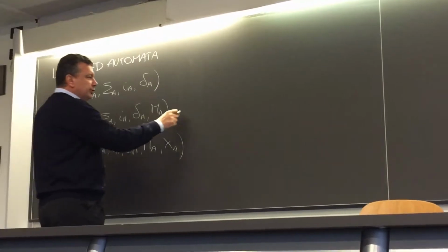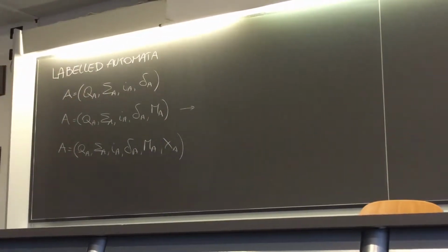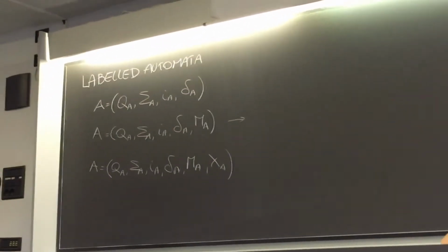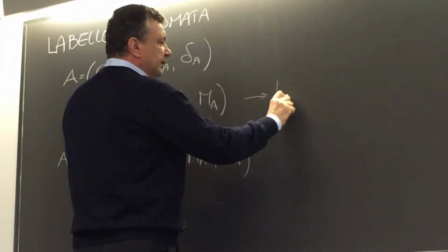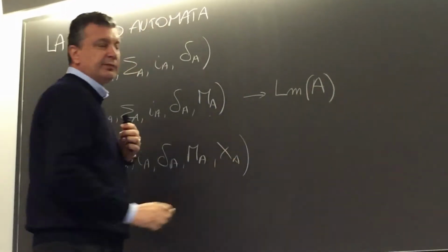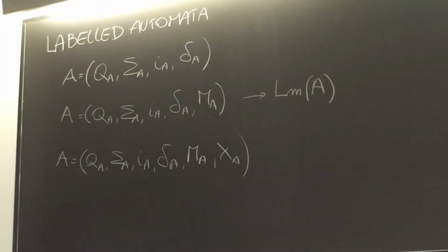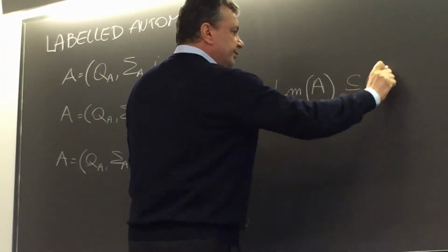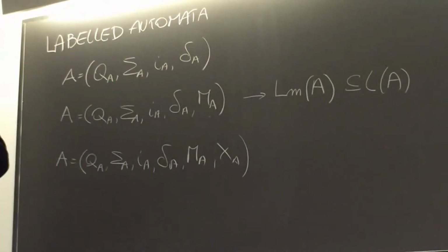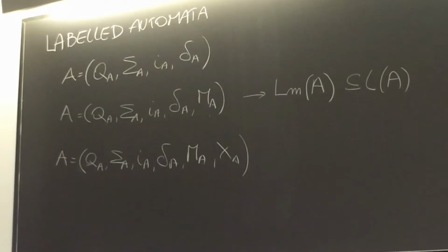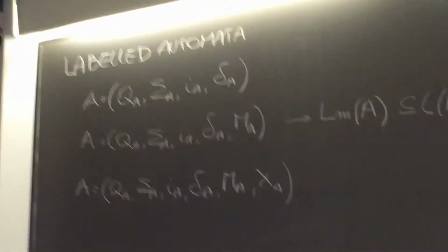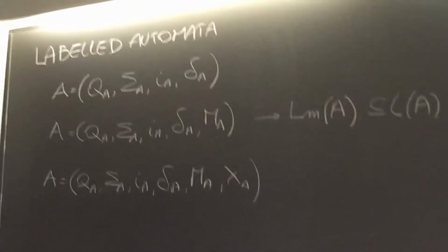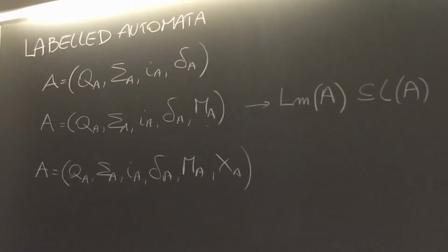Basically, here we introduce marked states, which represent goal states, the objective of our control. So, states that we want to reach. And here we define a marked language as a subset of the closed language, which has the peculiarity to contain only those strings which bring you to a marked state. So they are basically the path towards your objective. So the marked language contains the so-called legal behavior.